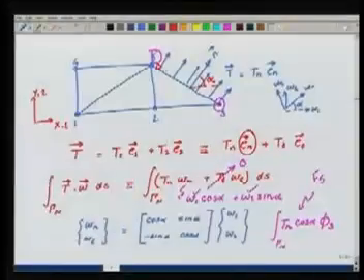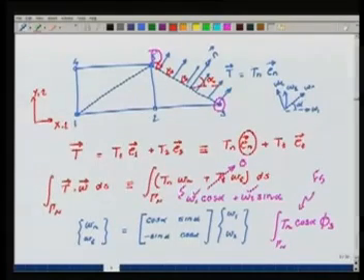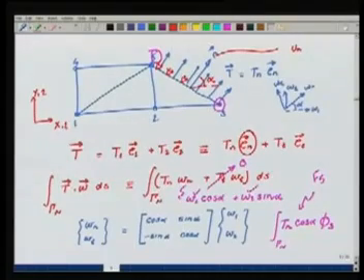What about an inclined displacement condition on an inclined edge? For example, if I have this edge and instead of this I have displacements given here, let's say rollers, that the normal displacement is 0. Okay, that condition, that constraint has to be imposed. So what does this mean? This will mean in this case that un is 0. Now un is given as a combination of u1 and u2 as u1 cos alpha plus u2 sin alpha. That has to be 0 on this edge.